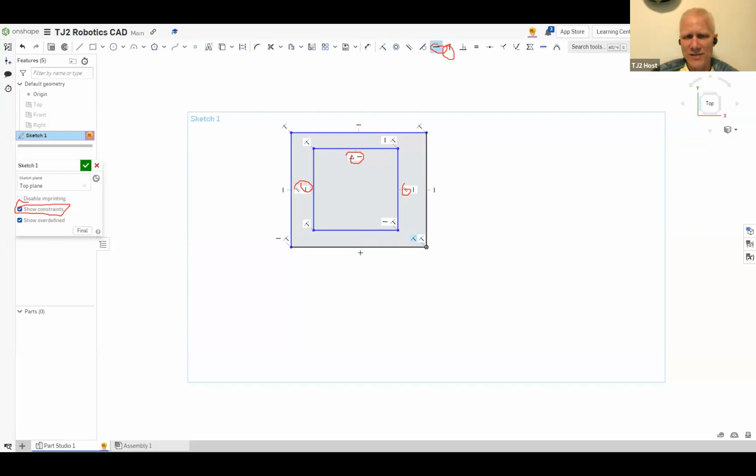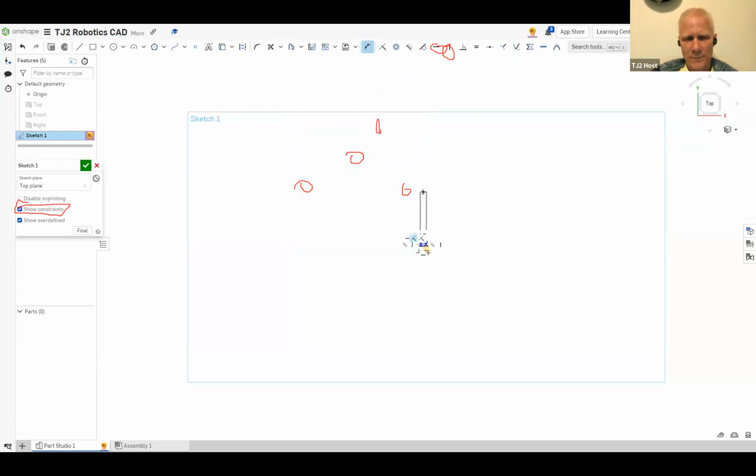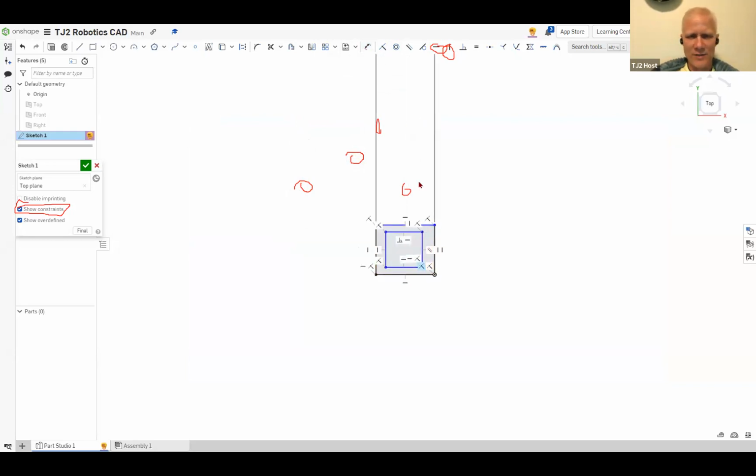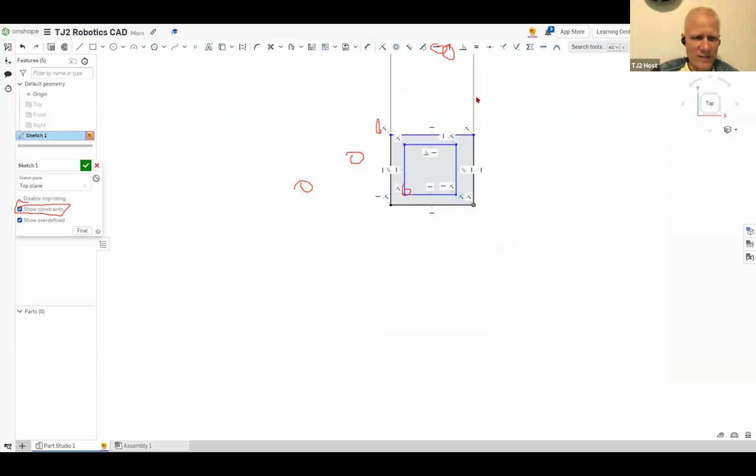And now we have to put the dimensions. To put the dimensions in, you go into dimension mode, right? Yep. And you make these lines 1. Click on the line and then drag your dimension up off the part. Yep. Drop, click, and then put a 1 in. Just type 1. Enter. Yep. And so now you have to zoom in. Let's turn off the constraints, we don't need to see those anymore. Turn off the constraints. Go over here. Yep.